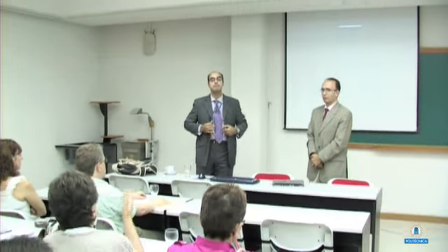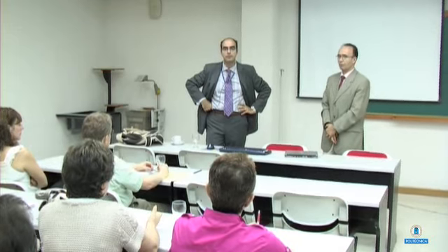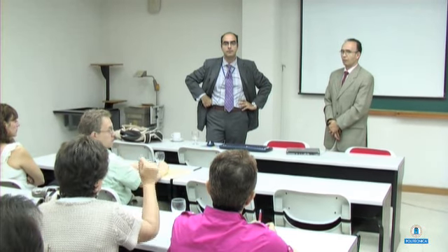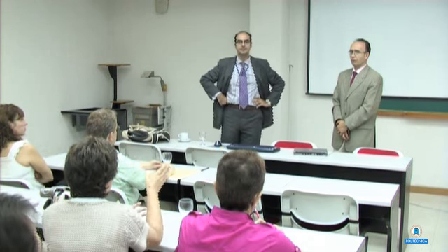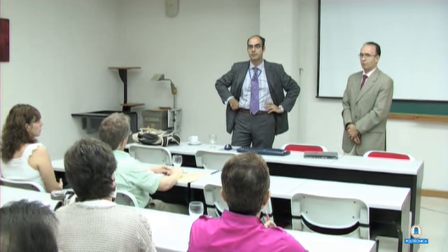I can imagine you have employed high impedance spectroscopy, and in impedance what is really difficult is the interpretation of the spectra, because probably there is a lot of information behind it. But I could see you have determined the resistivity. Finally, that is the parameter. Have you tried to obtain the same parameter from another, more direct technique?